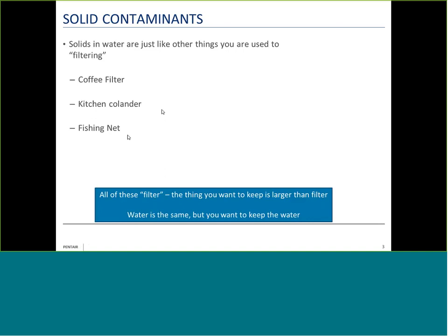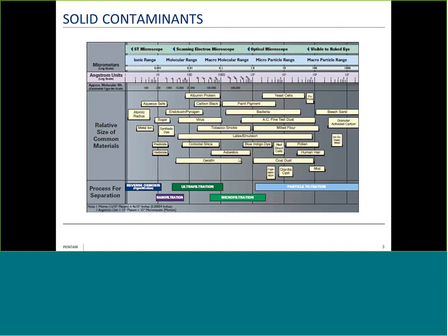And as it goes through the treatment process, you have pre-chlorination and flocculation. And flocculation is normally assisted by chemicals like aluminum sulfate, which will precipitate out particulate as it moves downstream. Well, that's typically added in excess, more than what's needed to get as much of the debris out as possible after the settling tank. So some of that chemical gets pushed downstream, and where it makes it out to the final dispense point, picking up turbidity on the way and settling it out.